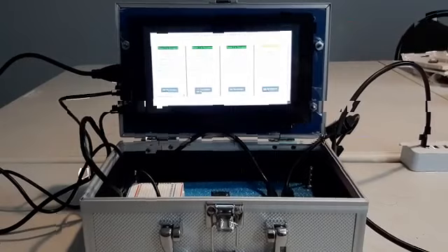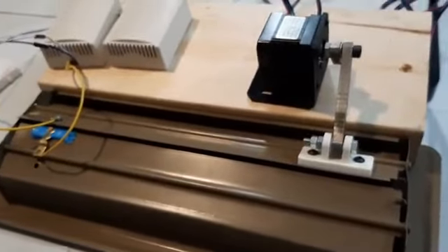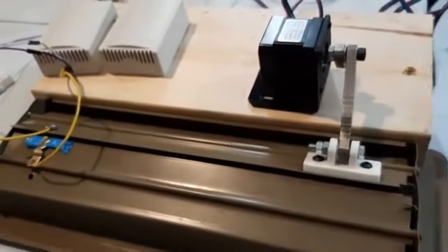Now I put the damper at 50%. After setting the damper set point to 50%, I click on apply parameters and then exit from this window and wait until this damper set point is applied in the set points shown in the HMI. You see here the damper set point has been applied, and now we are waiting for the motor to operate, and it opens the damper by 50%.